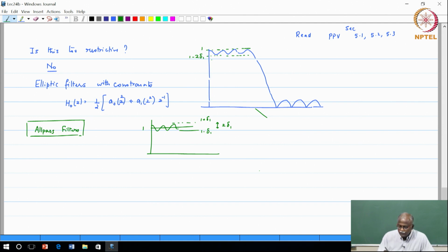So, if I were to plot the magnitude squared, |H0(e^{jω})|², this would be squared. So for the squared response, if I call this delta, that is the total deviation for the squared response, what will this be? This typically would have been called delta 2. When you square it, it will become delta 2 squared, that is the stop band energy, and because of the elliptic filter property, we specify that this is also equal to delta.